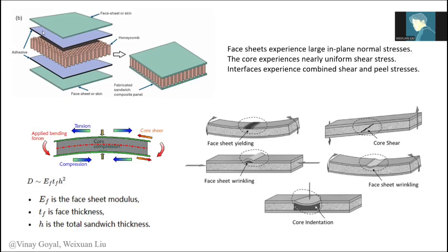For the adhesive, if you don't want to model it, it's totally fine. You can just extract the stress to see whether it will fail at this point. If you do want to model it, you could use a cohesive surface or element deletion for these kinds of materials.